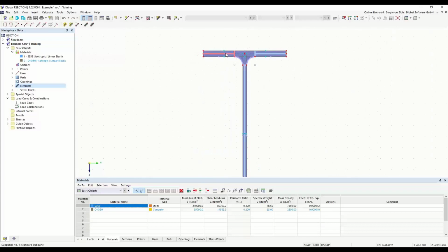What you can see here are the sub-panels, and these sub-panels are automatically generated based on the standard selected in the base data dialog, and these cannot be changed. If no elements are defined, the cross-section classification in the design modules of RFEM or RStab is not possible. And it's also not possible to do a calculation of the effective cross-section if no elements and no subpanels are defined. In the design add-ons of RFEM or RStab, like a steel design, the cross-section is then designed according to the cross-section class 3.